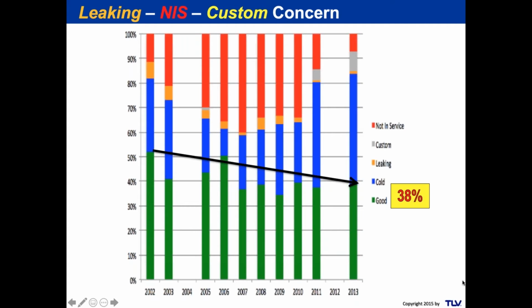The original designers said you need to have 100% of the traps working, with a reasonable amount of redundancy, to have proper operation of your plant. And this plant has decided to allow those traps to go down to 38% good and 62% not good. Do you think that's a relatively safe site? Do you think that site can operate anywhere close to benchmark? I mean, it's like valving out 62% of your traps and not having them there doing their job.